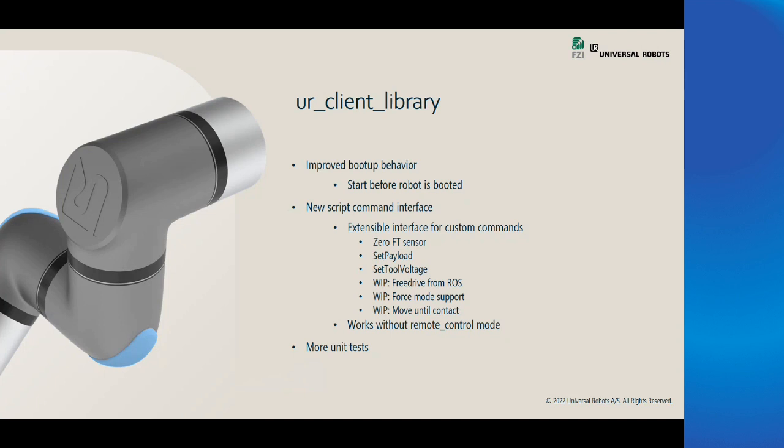So with that new scripting interface, you won't have to set the robot into remote control mode in order to do such things. However, you'll have to make sure that the program is actually running. What we currently already have, if you're using it as a ROS driver to actually move the robot, is support for zeroing the force torque sensor, setting the payload, and also setting the tool voltage. There's ongoing work about these three things, which I'll talk about in a second as well.